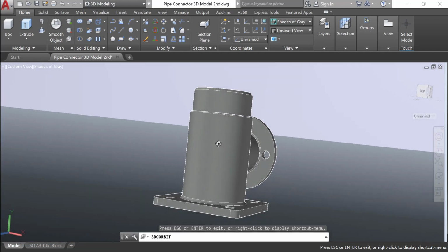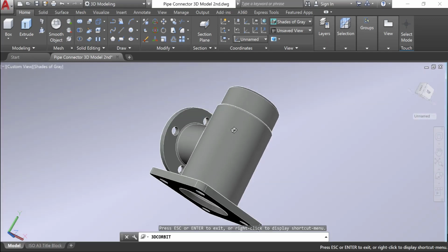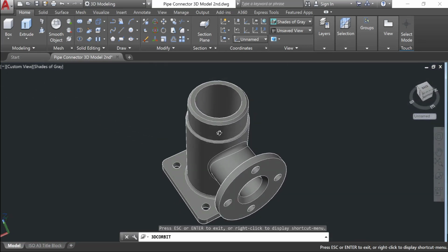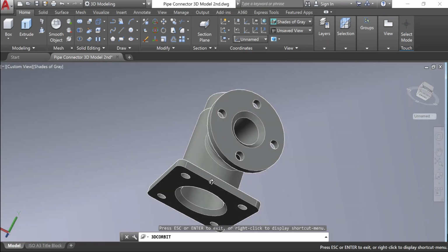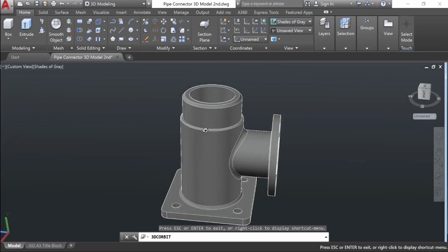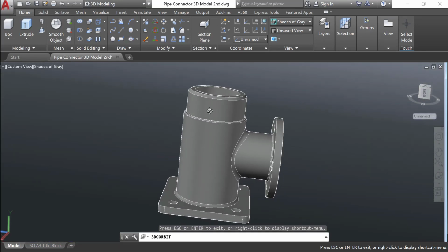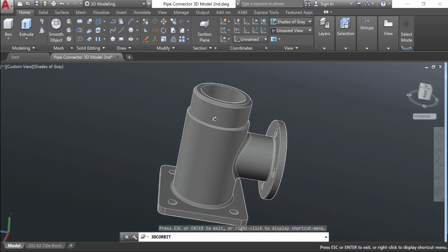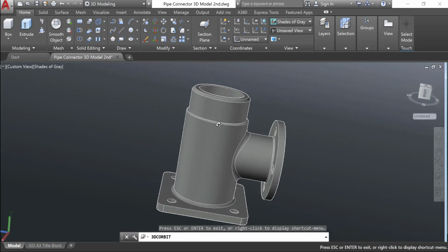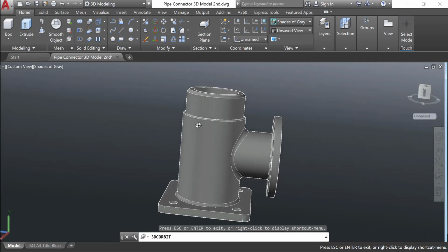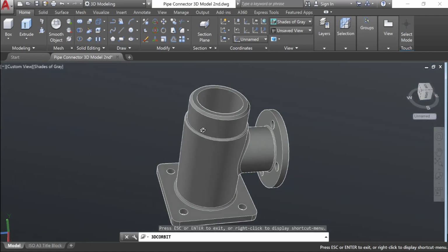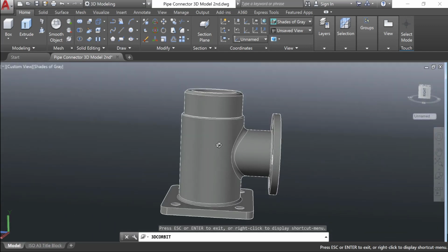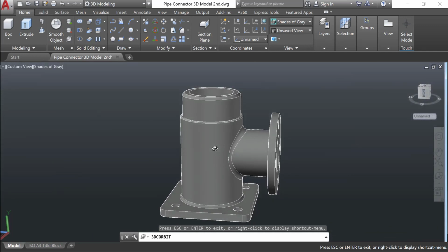Today we are going to draw this 3D modeling of the pipe connector, which is, you can see the tube, but it's not complete. You can see it has the inlet and 2 outlets. So we draw it. We won't make any thread in here, so we just use simple tools: circle, extrusion, subtract, fillet and chamfers. So rectangles. Those are, I think, the majority of the tools or commands we will be using here. So stay tuned, as we're gonna discover a lot in this video.